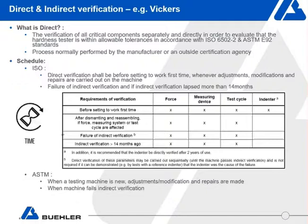And for direct verification, the schedule within ISO says that you need to do this verification for the first time when you're working with your machine, or whenever you do any adjustment, modification or repairs on the machine. And if you haven't done indirect verification for over 14 months, then direct verification of your machine should be carried out.